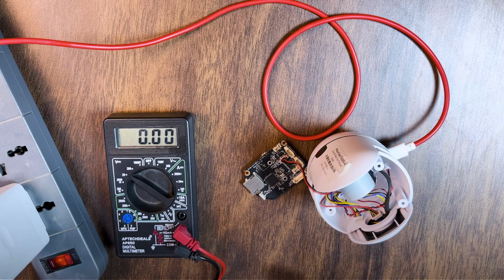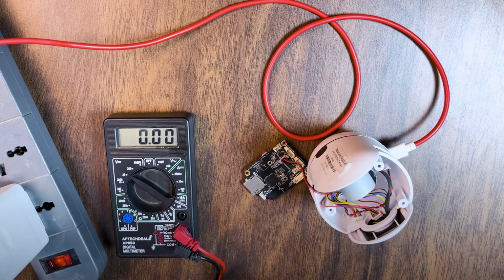Now, this is one way to figure it out using a multimeter, which we did right now: the ground, RX, and TX. However, whatever behavior we saw on the RX and TX could be a little bit different across different motherboards. Therefore, the other method to verify it is that, because we know that either of them is the RX and the other one is TX, just connect it to your UART to USB converter, TTL reader, and whatever port gives you the output on your Picocom or whatever you're using as the serial reader software, well, that is indeed your TX port.